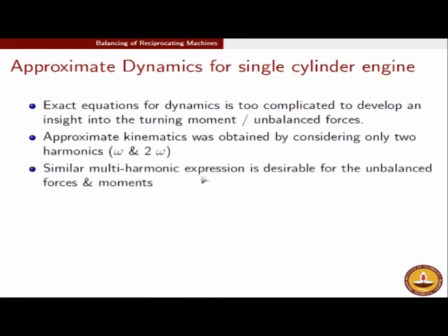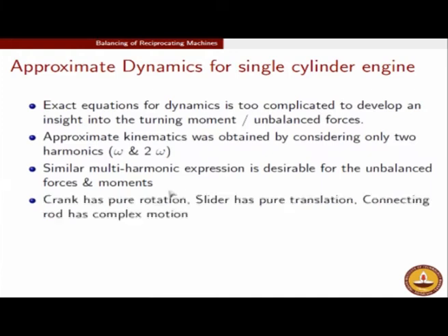We want a similar multi-harmonic expression, and that is very desirable for the unbalanced forces and moments, because most of the time in vibration the frequency of vibration is very important from the design perspective. If you know the harmonics and the amplitudes associated with them, it will be of great help in designing appropriate mounts, for example.